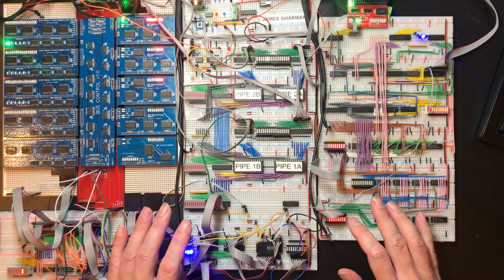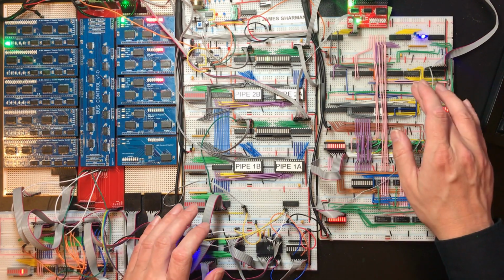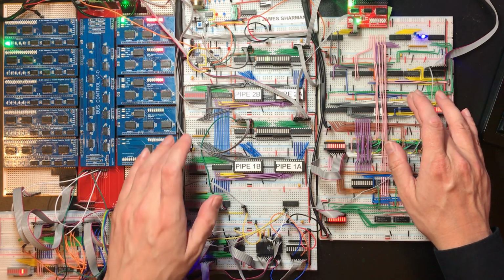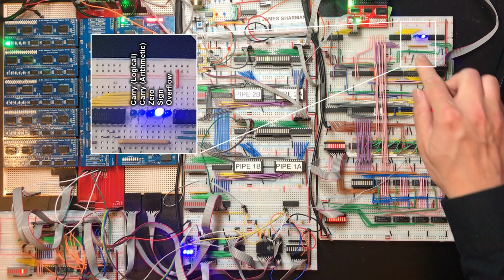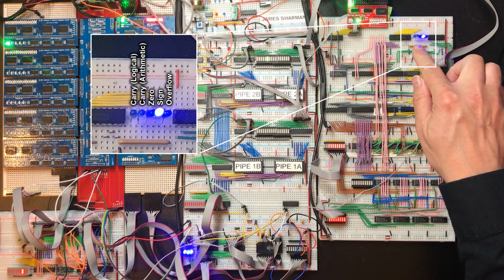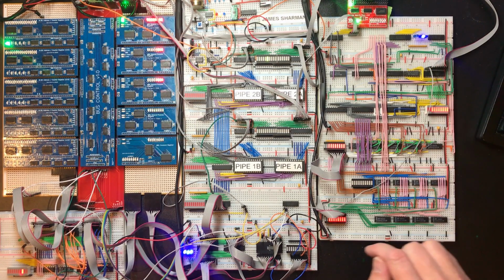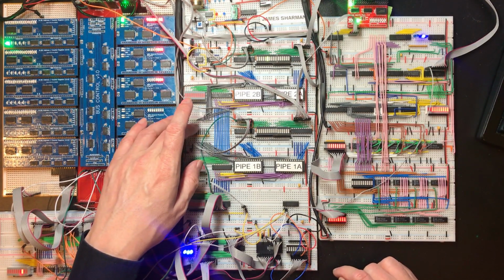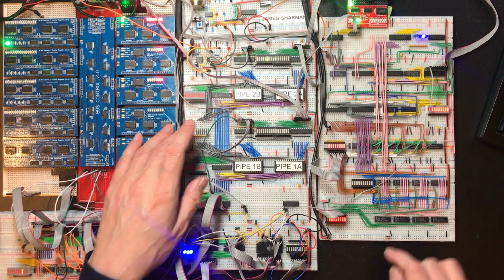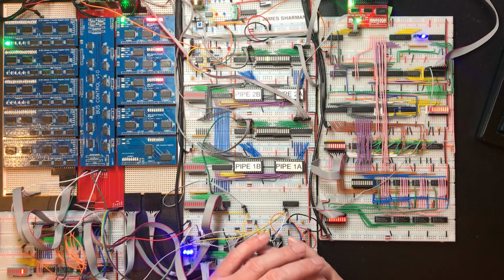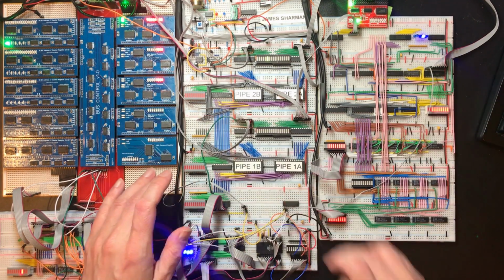We're going to be looking into flow control, and to do that we need to connect the results from the ALU back into the pipeline. So we have a total of 5 flags here: the logical carry, arithmetic carry, zero, sign and overflow. And we've got a number of spare control lines into the pipeline. So we've got 7 spare lines, 5 flags, and this video is going to be entirely about what we can achieve when we connect those to here.